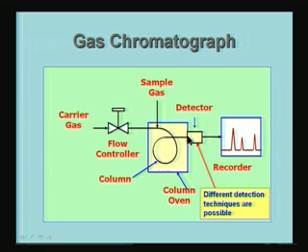So, if you look at the gases coming out here, it will be carrier gas plus the highest speed gas, the one which moves at the fastest speed will come first, and then after a gap the next one will come, because we have introduced a sample which is in the form of a pulse. So, the first one to come will be the gas which moves fastest through the column, after some time the next gas will come, and so on. So, by the time you come here, the gases are coming as separated species.